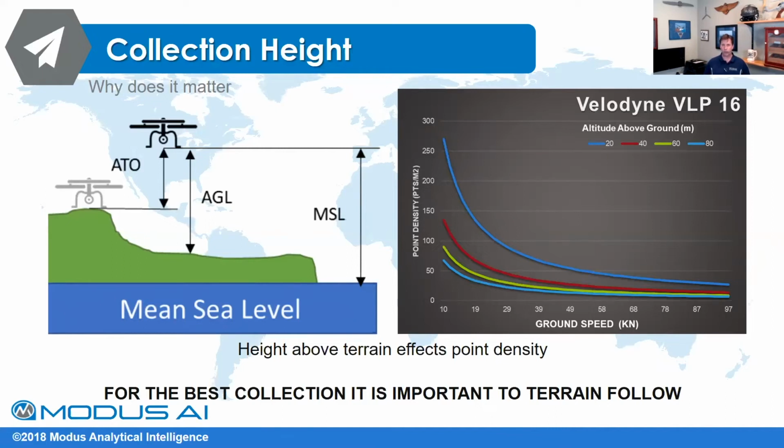This is typically what I use, because a lot of what I'm collecting is map of the Earth. And the last method is mean sea level, which is a barometric standard. Don't ever use that. Just don't. But I need to mention that these different standards are out there that you need to consider. If you're Part 107, you should know this, but for the folks that aren't aware, this is important.